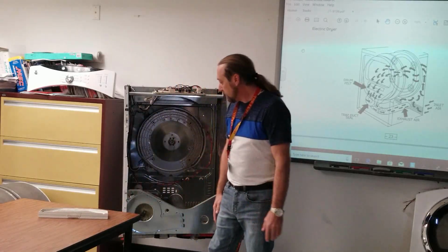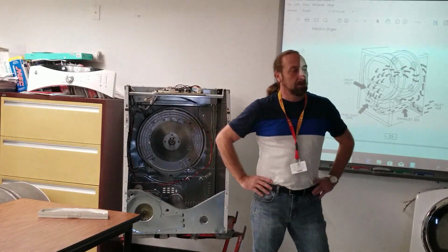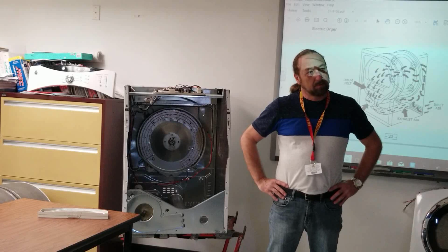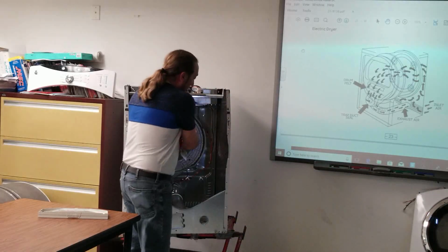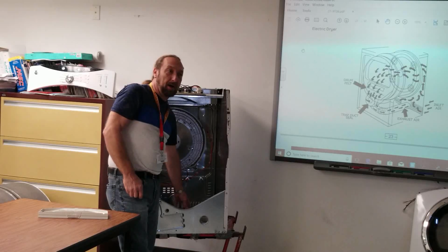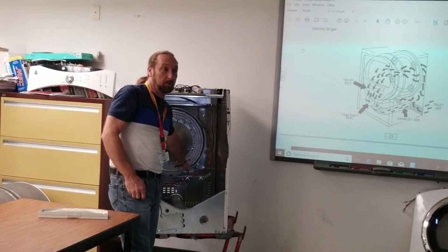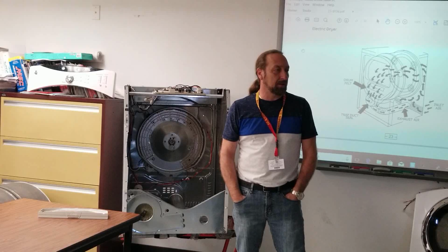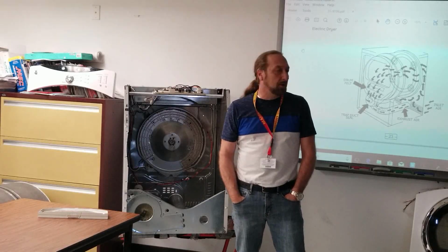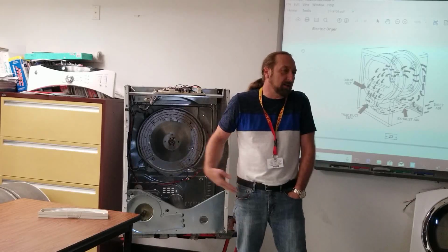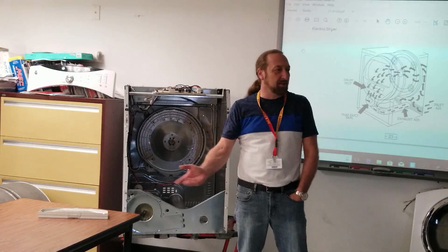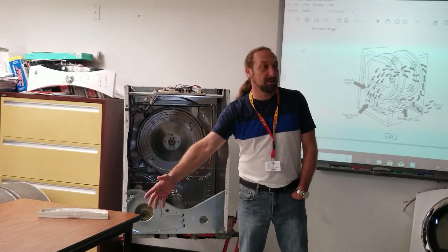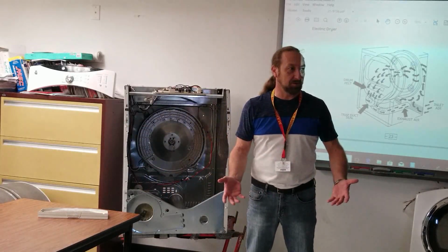No. Now let me ask you this. As you said, it works as a negative pressure. Now, the air goes through, so it's sucking air this way and then blows it out there. So the only positive pressure is after the fan going out. Yeah, what I was saying is that all this lint will not stay on the blower and make it unbalanced, or if you didn't put the filter. It could, because that air is filled with moisture and, you know, it could stick to the fan. But like I said, the filter is only 10-20%. So what's the difference if you had 70% passing through or 100% passing through? You know what I mean?